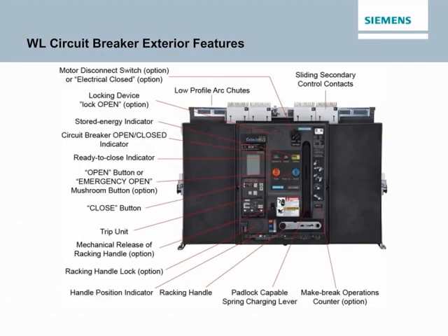WL circuit breakers can be fused or unfused and delivered with any of these operating mechanisms. Manual operating mechanism with mechanical closing, which is standard. Manual operating mechanism with mechanical and electrically interlock closing. Motorized operating mechanism with mechanical and electrically interlock closing.